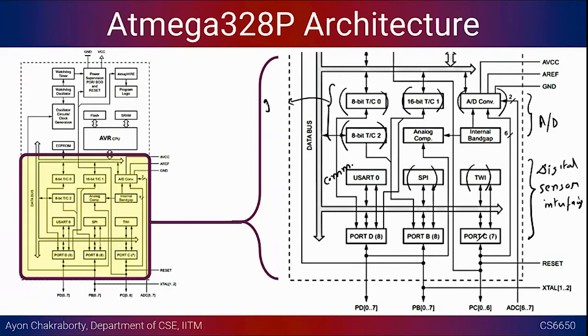Suppose you want to do some kind of sensing where you want to transmit a certain signal. Let's say you have interfaced a speaker, where you want to send out a sound signal, an acoustic signal, and then try to get the reflections coming back. Based on that, suppose you want to implement some sensing solution. So these timers would be used to generate signals, which is very useful often. If you want to not just have passive sensors, but do something actively, you want to send out signals, and based on how the signal interacts with the environment, you want to draw conclusions.